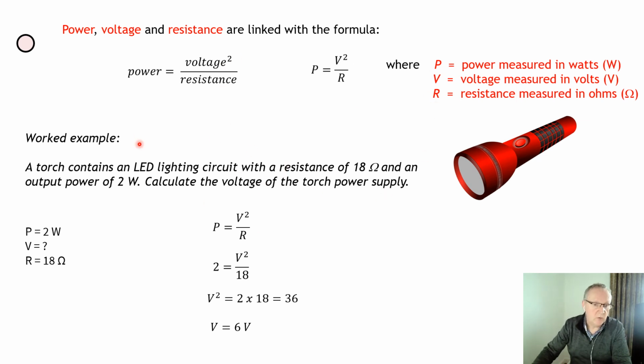Okay, and that's the 3 electrical power equations, along with the power equals energy over time general equation. And so the key thing is getting the information from each question, putting it down with the symbol, and then figuring out the right equation from that. Bear in mind, closely linked to all of this is Ohm's law equation, V equals IR. So bear in mind, you may have to chop and change between equations and also use Ohm's law.